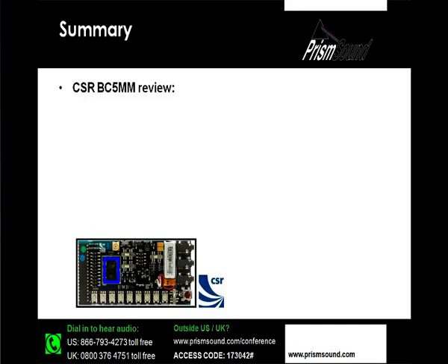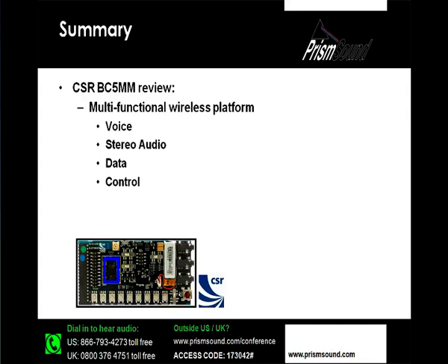Hi, thank you, Simon. Yeah, we saw earlier that we were using the BC5MM on a 1645 board, as you can see down here. This is a multifunctional platform where it's user programmable, both in terms of the DSP and in the host functionality. You can implement various different platforms on it for voice, stereo audio. You can either pass data over it or control, as I said earlier about AVRCP, where you have a stereo headset which has transport controls on it, and those go back over Bluetooth, because it's a bi-directional link, back to your MP3 player to control the audio, whether it be the volume or track select.